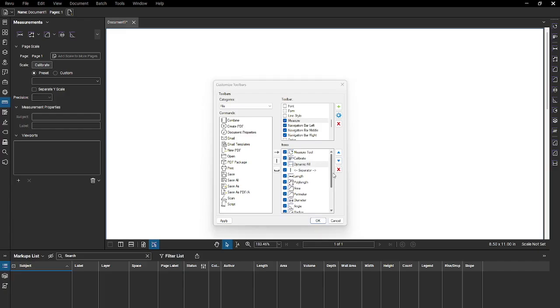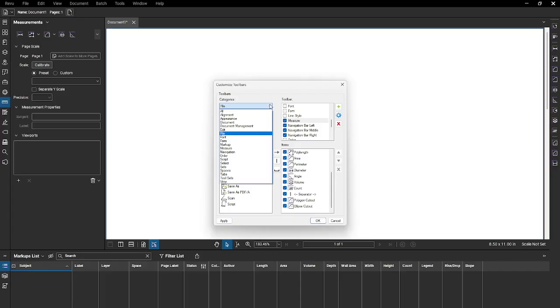Click on the radius, and then click on the Delete button to remove it from the toolbar. Now go to the categories dropped down on the left and select Measure to view the measurement functions. You want the individual tools, 3-point radius and center radius, in this toolbar, instead of just the general radius one.